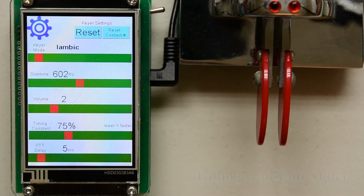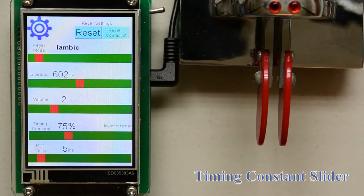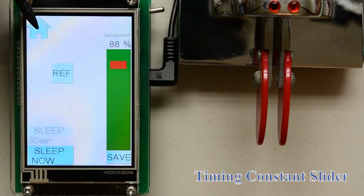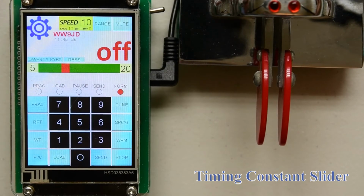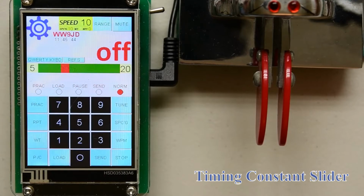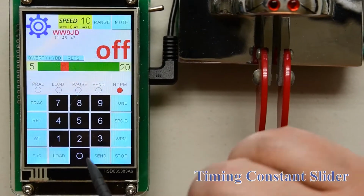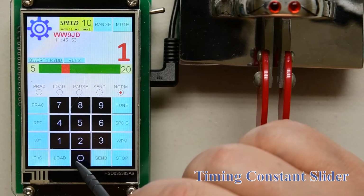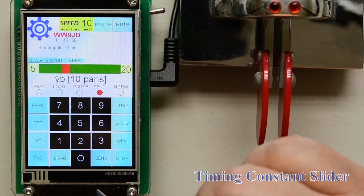The timing constant changes a variable in the speed setting algorithm in the keyer so that you can set your keyer to exactly the speed that you intend for it to be. For example, my keyer is set to 10 words per minute right now. If I come back to the beginning, I have a file on the micro SD card, 10.txt, that is the word Paris 10 times. It should take 1 minute to send. We'll talk about sending later, but to send that file, 10, tap send, and it's going to load.